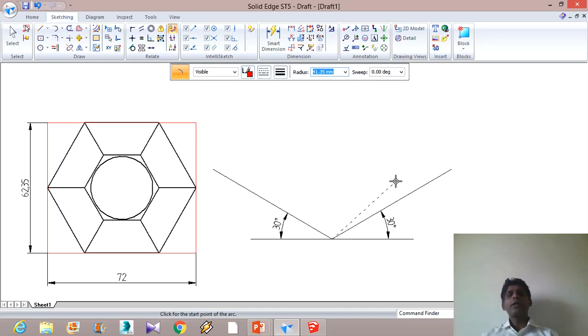But when you are doing it manually, you have to actually calculate the isometric of 72, that is ISO 72, that is nothing but 72 multiplied by 0.81649, and whatever length you get, that length has to be marked here. But here, however, I am going to draw the view, that is why I am going to mark this as 72 mm only, right? And same is the case on this side also.